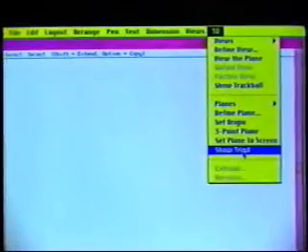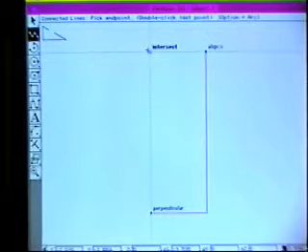The first thing to do is to go to the 3D menu and ask to show the triad. This brings this little marker over here, which is an origin marker, which shows the reference planes. You'll see that in a moment. Then I'm going to pick the connected line tool, and using the connected line tool, I would just begin to draw a simple rectangle. As always with Vellum, you have your construction lines that the drafting assistant provides, and I can sketch out the beginnings of a rectangle. I could come up to this point and get my intersect, but I'm not going to click this point. This is how I would work in 2D.